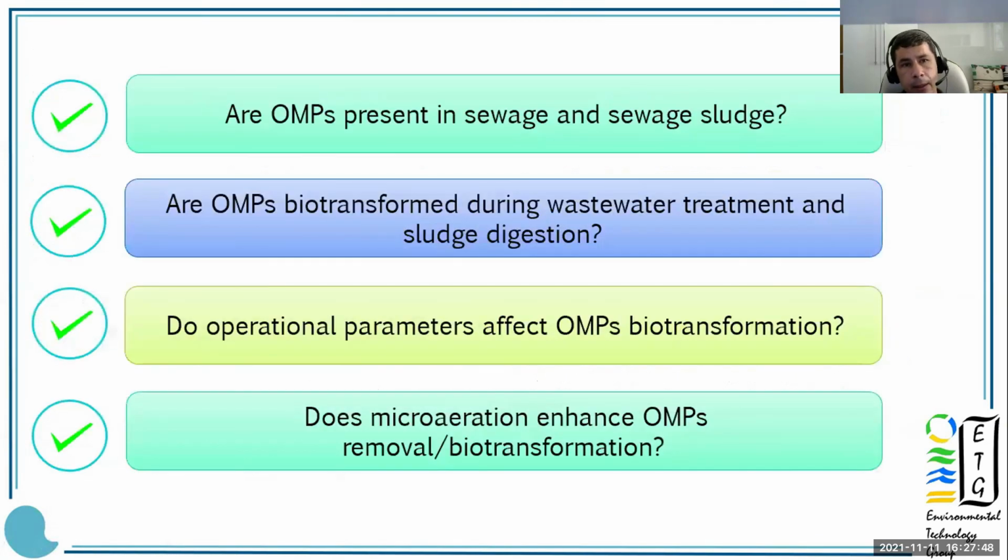And finally, some conclusions. Are OMPs present in sewage and sewage sludge? Yes. Are OMPs biotransformed during wastewater treatment and sludge digestion? Most of them, yes, in different percentages of removal, but most of them, yes. Do operational parameters affect OMP biotransformation? Yes, it will depend on the parameter. Temperature, no. Sludge age seems not to affect it.